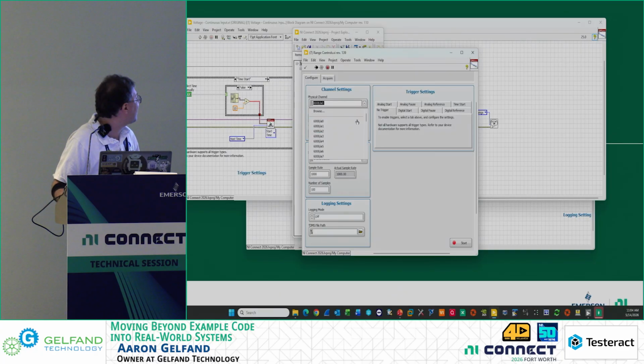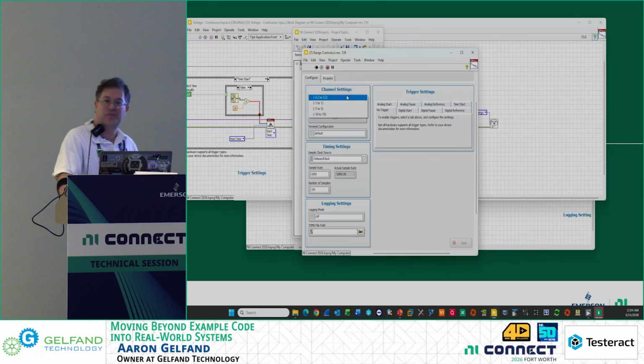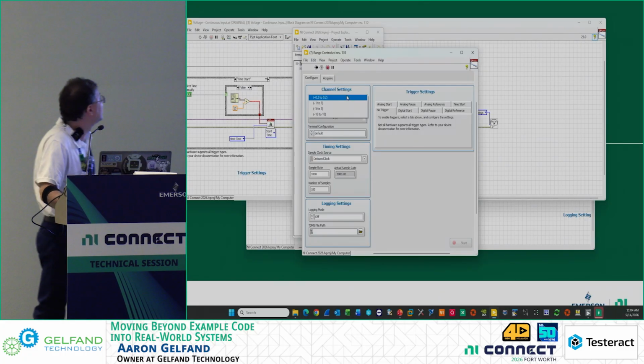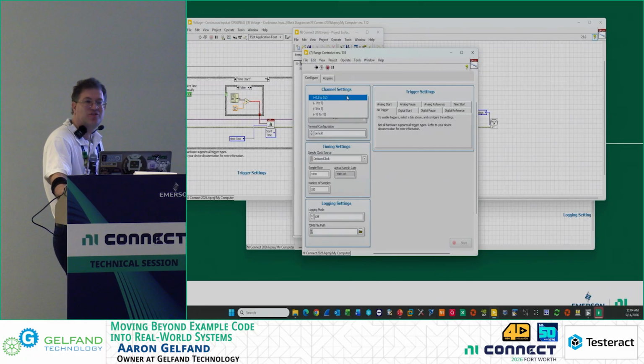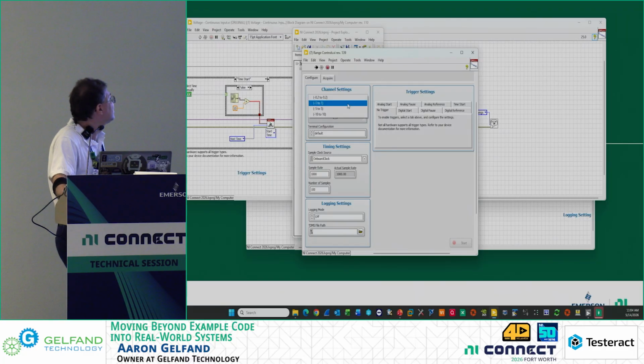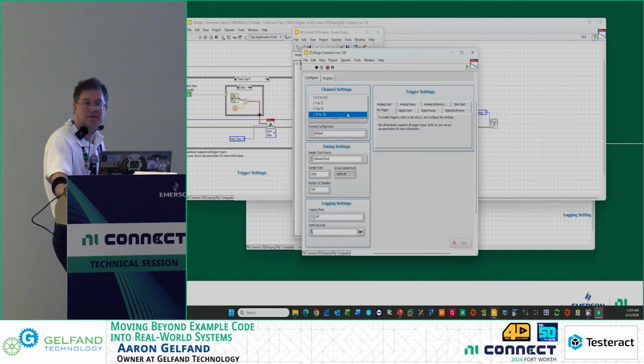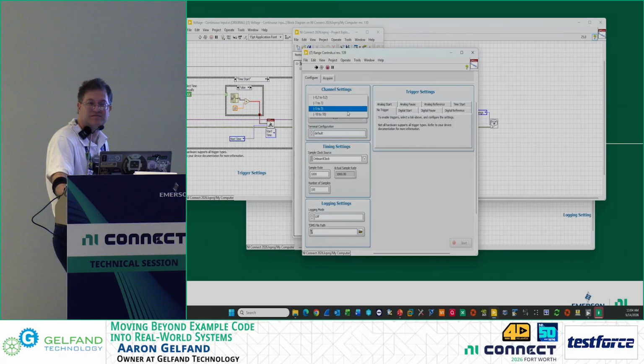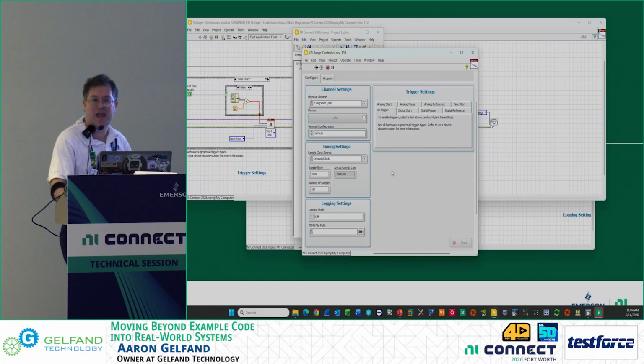And if I go ahead and do this for cDAQ5 module AI0, which is a simulated NI 9425 analog module, we see that my valid ranges are -0.2 to 2, -1 to 1, -5 to 5, -10 to 10. I'm guiding my users to make fewer mistakes and safeguarding my users. And that gives me a better program.